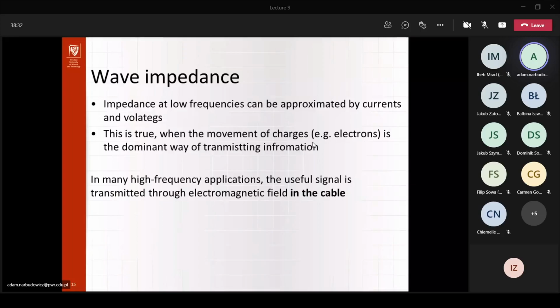Basically this means that you do need a conductive copper, but the signal is created mainly by the electric field in between the copper rather than flowing through the copper. This has to do with the fact that typically at higher frequency, your electromagnetic signal cannot penetrate very deep into the conductor.